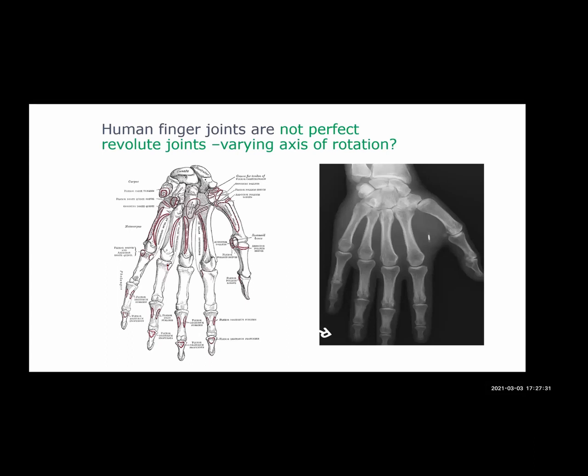So in the case of the leg, the hands, the arms, the shoulders, the elbow, anybody who's working with an exoskeleton has to know this: your joints are not revolute joints, which means that there is a varying axis of rotation. What I mean is, in terms of a mechanism, there is an instantaneous center of rotation that keeps changing. If you have a revolute joint, then the joint radius will remain constant, whereas in this particular case, that R will start changing, because the axis changes.